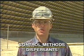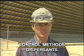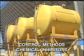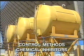There are several ways to control fouling in a heat exchanger. One way is to add dispersants. These will prevent insoluble materials like dirt from forming solid deposits. Another control method is to add chemical inhibitors that will keep chemical reactions from taking place. Or antifoulants can be added to the process streams. These chemicals prevent biological growth.